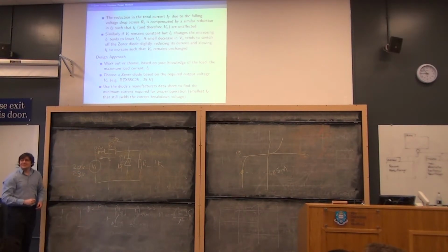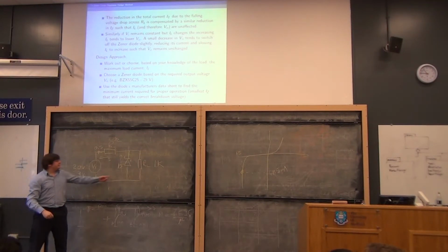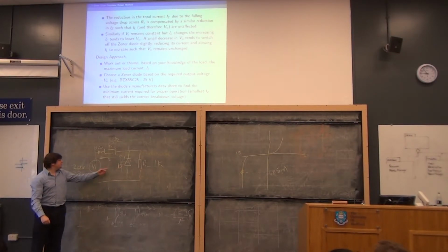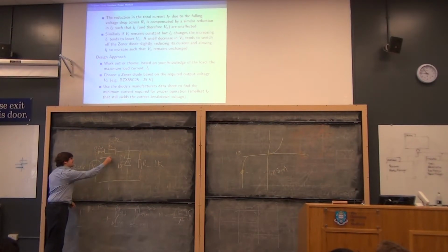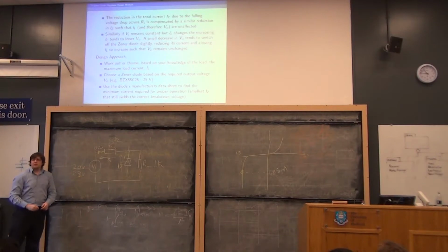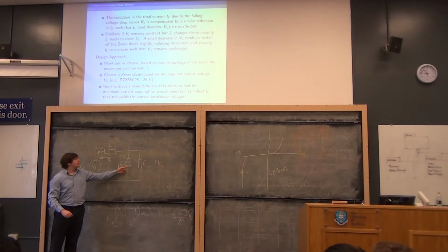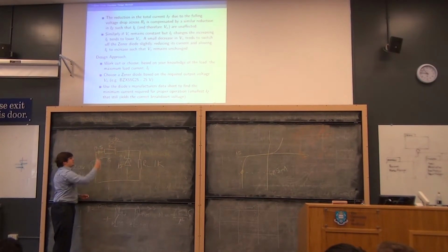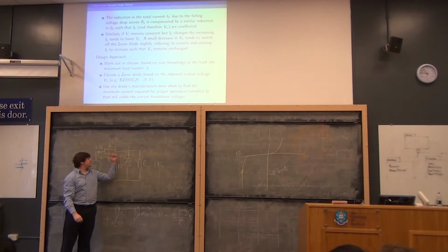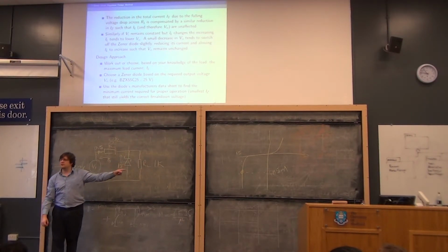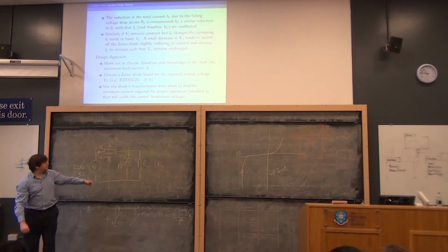23 is definitely prime. Right then, so now you've got 23 here. Now you've still got about 15 here. Now it will change a little bit because now there'll be 8 volts across there. So 8 volts across there, so we'll have 800 milliamps flowing. That'll be 0.8 amps. So we'll have 800 milliamps, we'll have 15 and a bit volts, but we don't know how many because we haven't looked at the curve. This curve will not be available to you. If you want it, you'll have to come up with a measurement system to measure it. We'll just say it's 15.